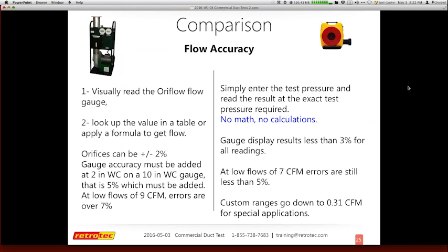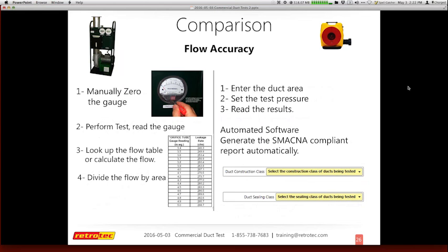So here's how simple we can do a test. We're actually going to hit set speed. You can easily start even at 1% because this is such a powerful fan that I can start at 1 and then I can slowly tap my way up until I reach the test pressure that I want to achieve. The channel A at the top here is the test pressure that I'm achieving. And these are actually my results that I have down here on the bottom half. I have the ability to turn on the add feature and make that go exactly to what I have. So here I have an older slide that's residential, but I can demonstrate that we can also make that at 4 inches of water column and get my results directly on this second line based upon the inches of water column I have here.